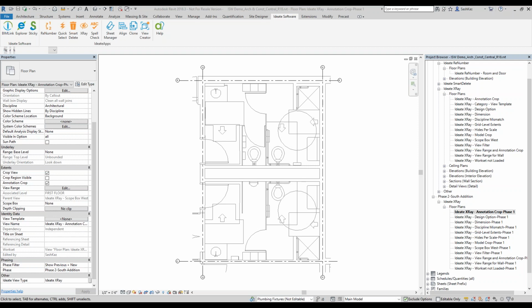It would show things like your room separation lines, those kinds of things, but those views actually don't go on sheets. So if you are exporting out to DWG and to PDF, then what you could do is use the final view or the sheet view instead of the working view. But if you want, you can give your path its own line style, its own name, and then you can turn it off in visibility graphics before you export that information out. It's a great question.